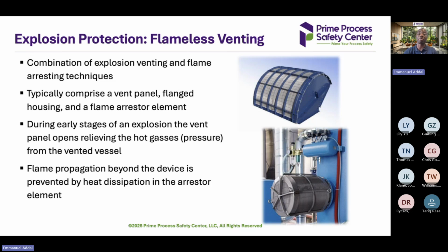A flameless vent is like a flame arrestor with a lot of meshes in it. In case an explosion happens, it has to go through those meshes, and by the time it gets out it has been quenched and has turned to smoke. In Germany, I witnessed such a demo where I had to use my hand, and I was really afraid. I thought it was going to blow out and I was going to die. But I used my hand to touch it during the explosion, and nothing happened to me, thank God.